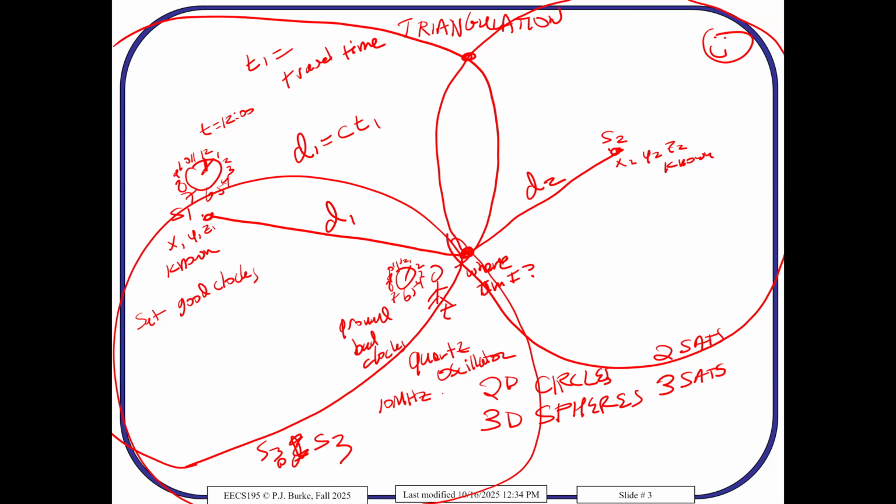And it's in all of the electronics that you use: computers, cell phones, laptops, everything. It sets the clock frequency of your computer. If the quartz oscillates at 10 megahertz and your clock frequency is 300 megahertz, it'll use that as a reference and multiply by 30.